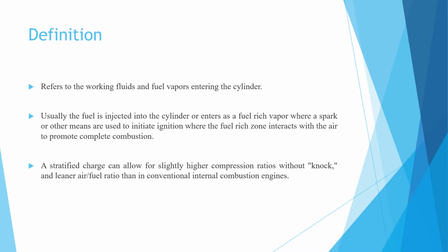A relatively rich mixture at and in the vicinity of the spark plug, and a lean mixture in the rest of the combustion chamber. That is, the whole fuel air mixture is distributed in layers or strata of different mixture strength across the combustion chamber, while the overall mixture is rather lean.